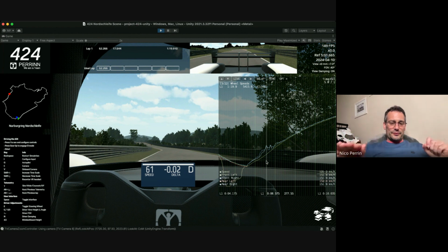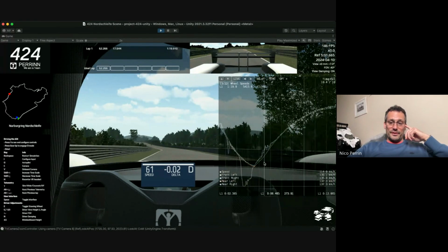That's because as soon as we touch the throttle, the mechanical diff is locking the diff. This is the most stable way to exit a corner. You lock the diff front and rear. And all you do then is control the amount of power going front to rear in order to avoid spinning the front tires or the rears. So here we are in a pretty good scenario, actually. They're sliding more or less the same amount. Okay, so I'm fairly happy with that.